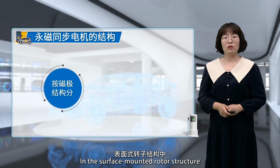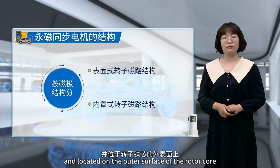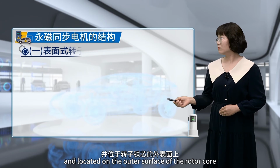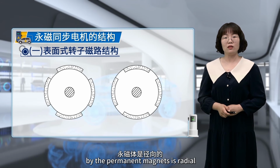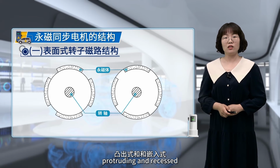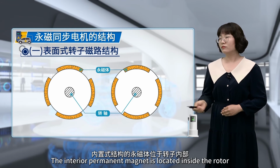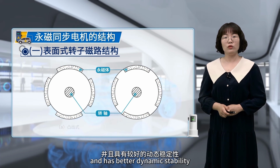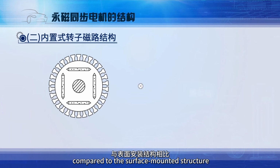In the surface-mounted rotor structure, the permanent magnets are usually tile-shaped and located on the outer surface of the rotor core. The direction of the magnetic flux provided by the permanent magnets is radial. There are two types of surface-mounted structures, protruding and recessed. The interior permanent magnet is located inside the rotor and has better dynamic stability compared to the surface-mounted structure.